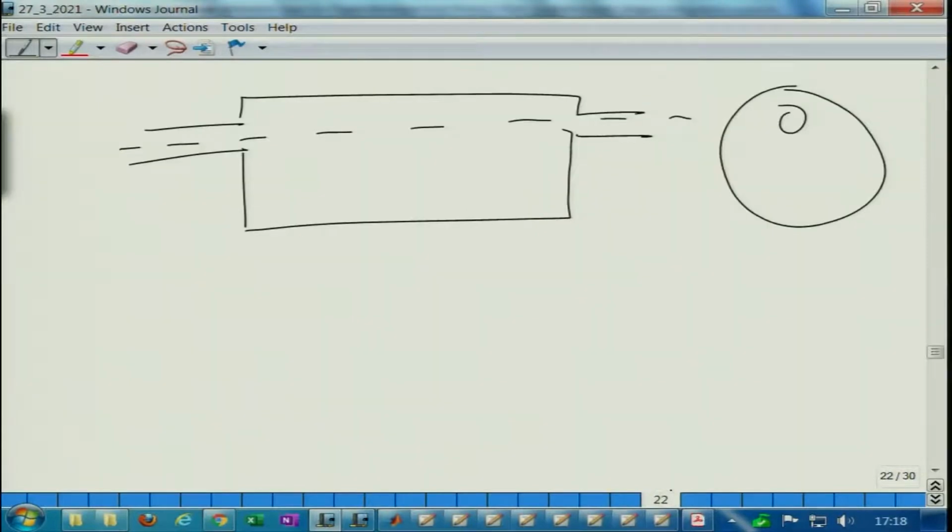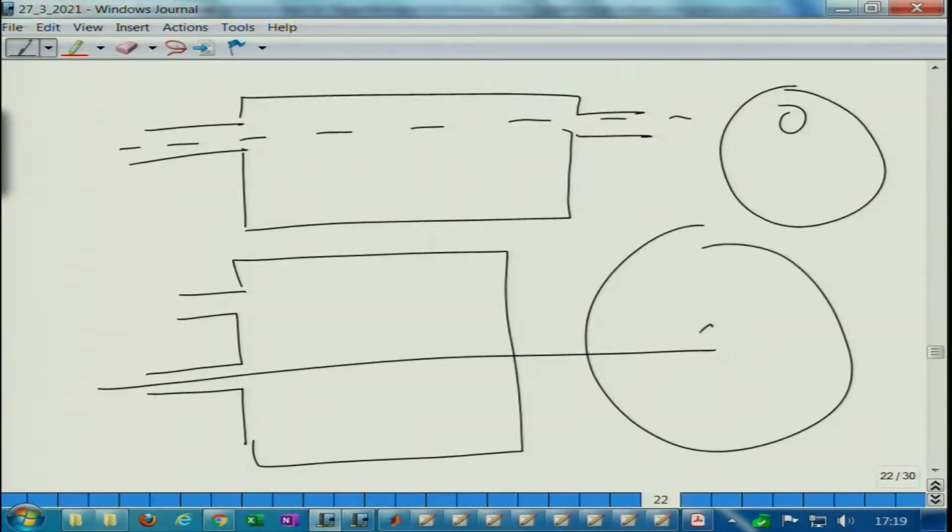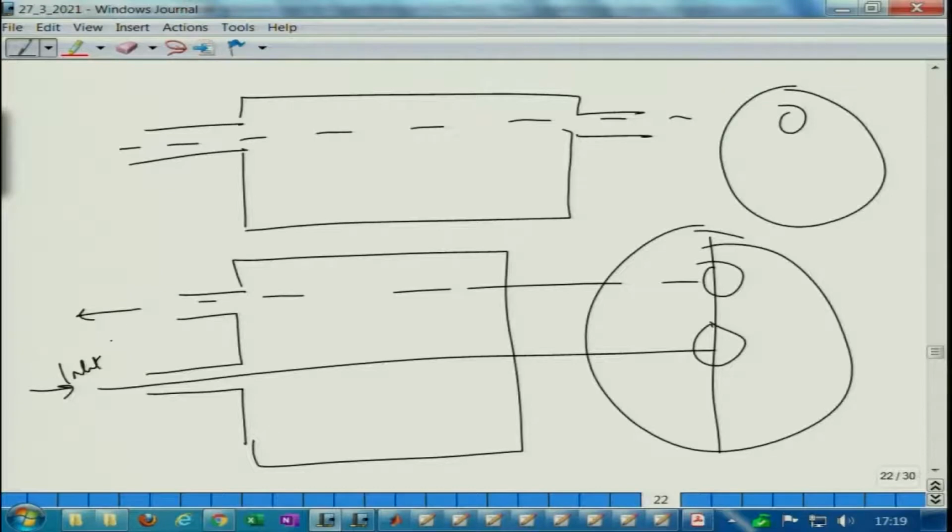So, before we actually run the code, we can use the same code to analyze a flow reversal kind of muffler configuration. So, let us say this port is concentric here, and this is something like this. So, inlet, outlet. Okay. So, inlet and outlet, and the length is L. So, what we need to do in the code is just put Z12 equal to 0. Basically, if you consider a coordinate system with Z equal to 0 here, with respect to port 1, this is also located at the same value.